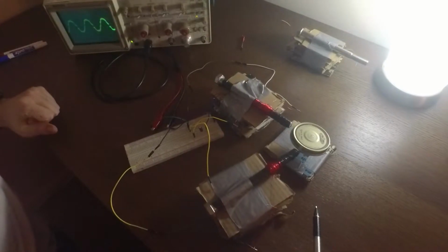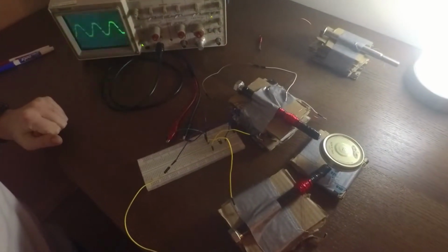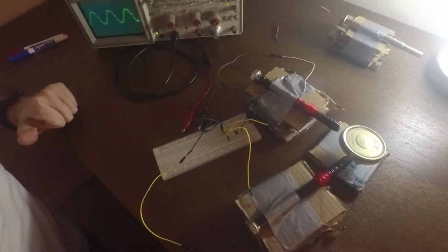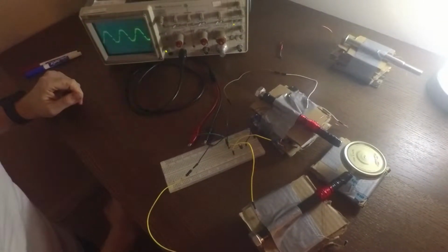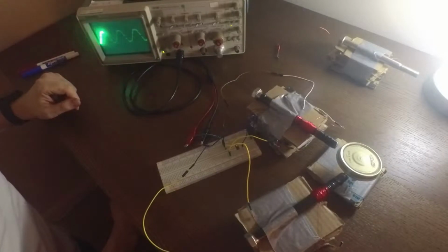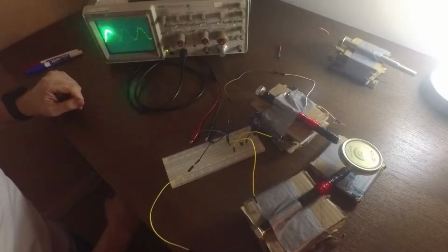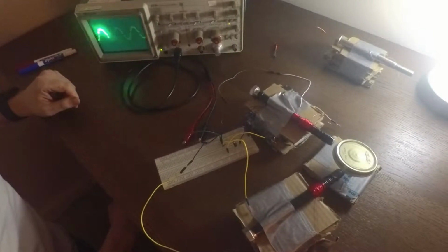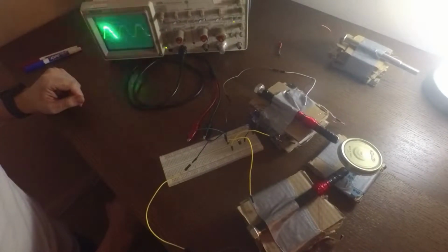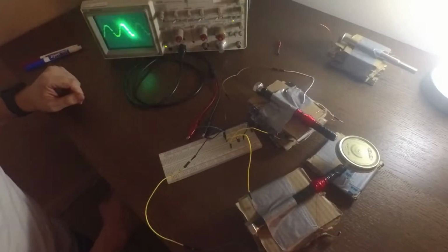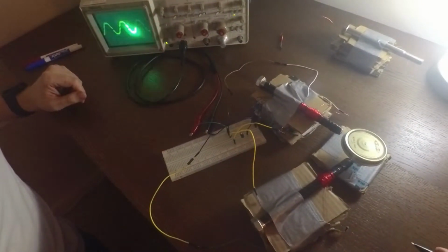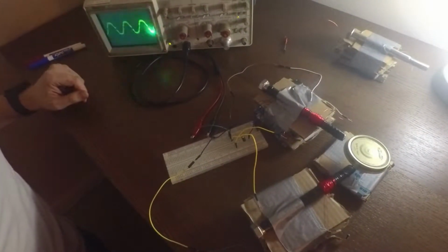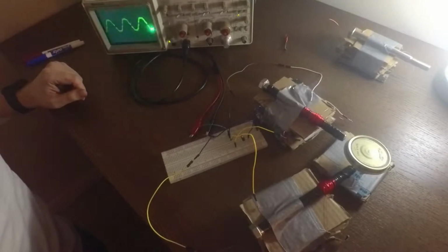There are a few factors that may be causing the motor not to operate correctly. The power supplied by the oscilloscope may not be enough for the coils to generate a strong enough current and magnetic field to get the rotor to spin. I did not come to this conclusion initially. At first I thought it may be an issue with the magnet wire I'm using potentially not being fully insulated, which would cause current to short out through the coil and not create a magnetic field.